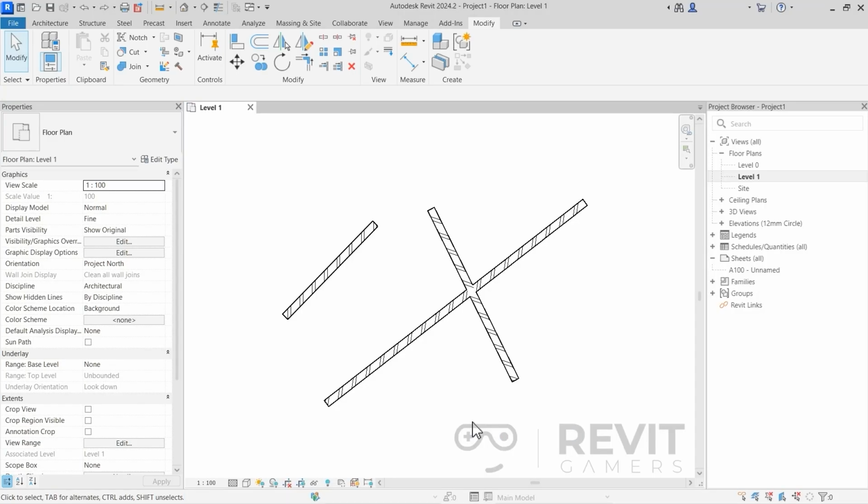As mentioned, the trim extend single element works like the trim extend to corner, but only changes the second picked object. Select the tool first, then click over the first object, then click over the second object. The first object remains unchanged, and the second object will be extended to match the extent of the first object. If the second object does not intersect the first object after the extension, it changes in length, showing that it meets the extent of the first object.